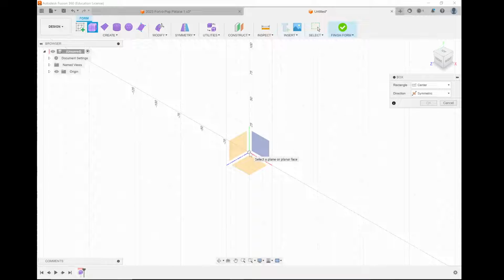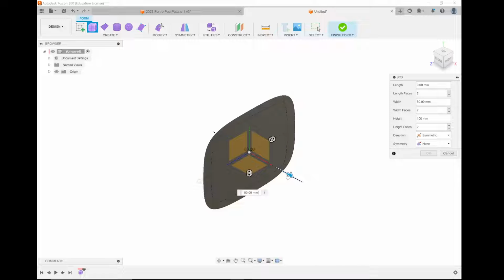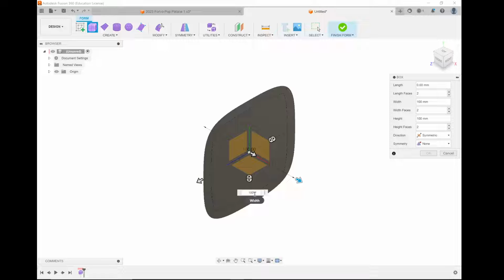I'm going to press my mouse over the center point. This is why we had to unhide our origin, otherwise you wouldn't find the center point. We're going to press this as our point location. I think you've got to press it once to get the plane, and then you've got to press it a second time to choose the location. And now we can pick the diameter, the size. I'm just going to pick a size like 100. Does that work? Ooh. 100 by 100.